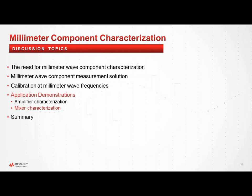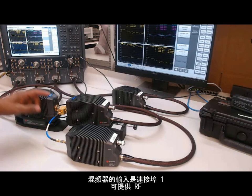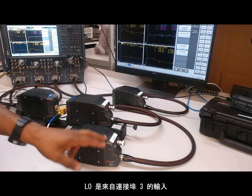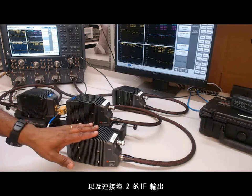Okay, so you've seen the amplifier characterization. Next, let's look at a mixer and how we're going to characterize that in the next demonstration. Welcome to the demo for the mixer. In this setup, we have the mixer here. The input to the mixer is port 1, which provides your RF. The LO is coming in from port 3, and then your IF out of port 2.